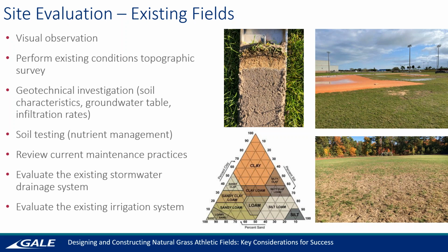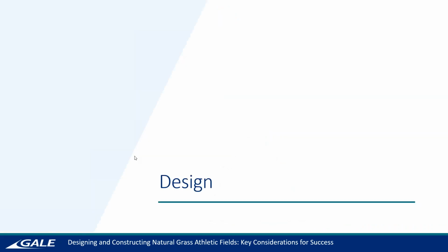And then your existing irrigation system, right? How is it working? Are the zones all right? Is the coverage the way you want? Do you have the proper pressure with your irrigation heads? Or are you getting those famous little donut patterns, little green circles around each head, and then the rest is kind of brown, usually an indication that you don't have proper pressure.